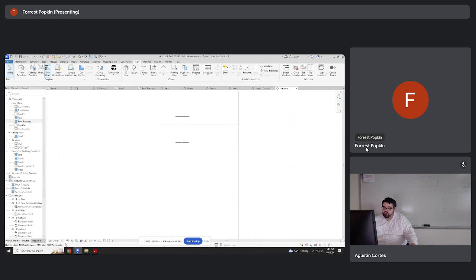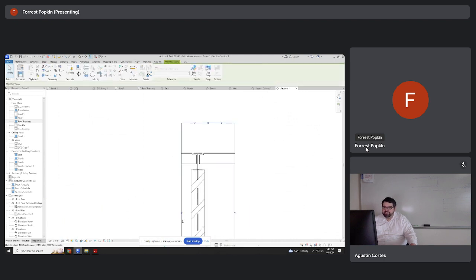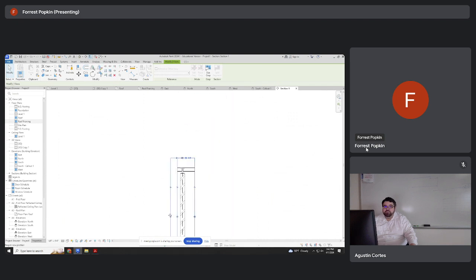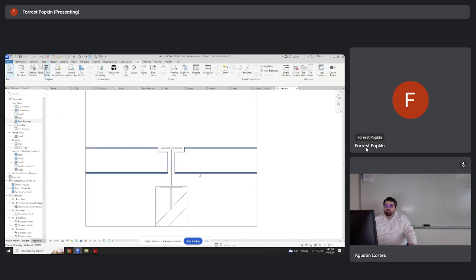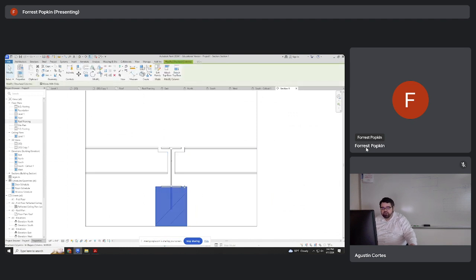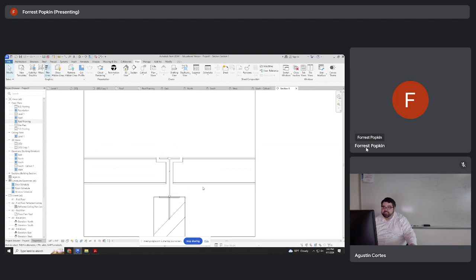And if I go back to my coarse view and make it a fine view, here we are. We're starting to see this detail up close and personal. I can actually go ahead and just focus on this one part. But this is important because if I were to show how I'm detailing all of this, this is a view that's of critical importance because I have my beam, my column, I have my girder, and I have my beam. So in this particular view, I have a few ways to go about continuing to add detail.